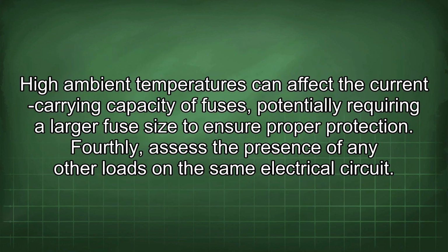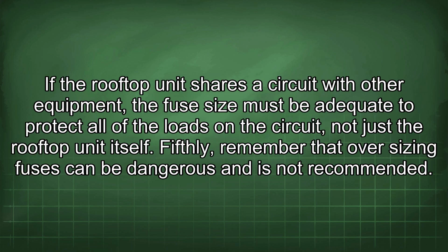High ambient temperatures can affect the current carrying capacity of fuses, potentially requiring a larger fuse size to ensure proper protection. Fourthly, assess the presence of any other loads on the same electrical circuit. If the rooftop unit shares a circuit with other equipment, the fuse size must be adequate to protect all of the loads on the circuit, not just the rooftop unit itself.